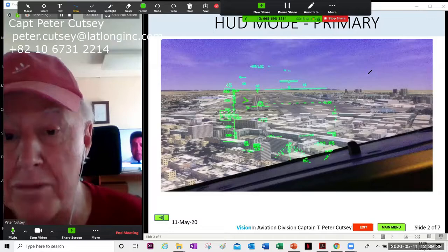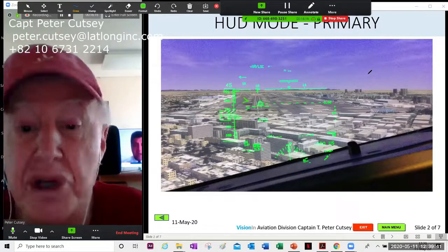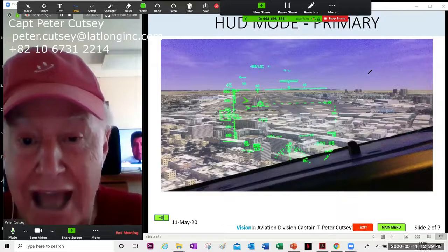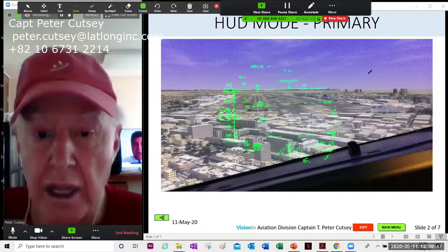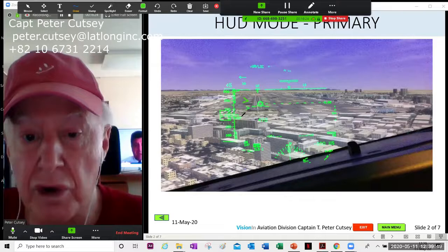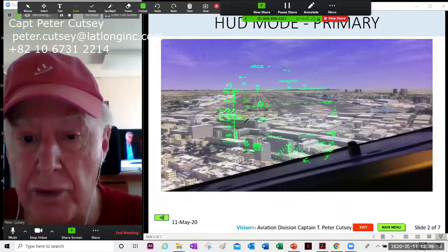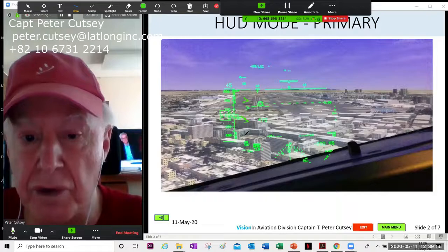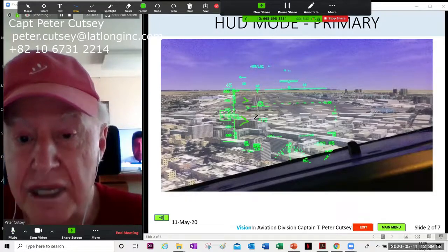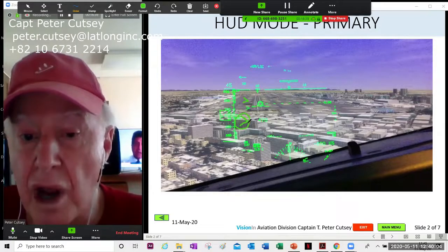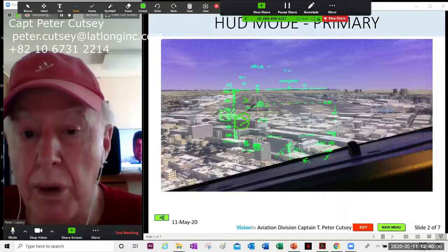All it means is that all the forces and all the energy that's happening is that the aircraft's energy is accelerating. Conversely, if you were decelerating, if you brought the thrust levers back and straight in level flight or whatever, and your airspeed was decreasing, the entire energy of the aircraft would be diminishing. Therefore, your symbol would be below the wingtip.